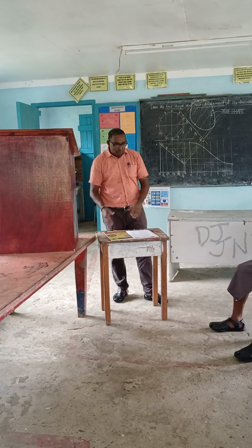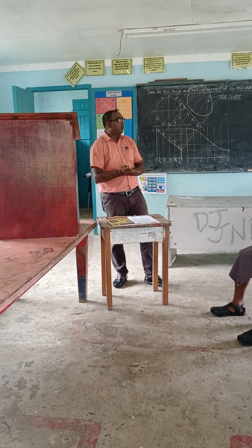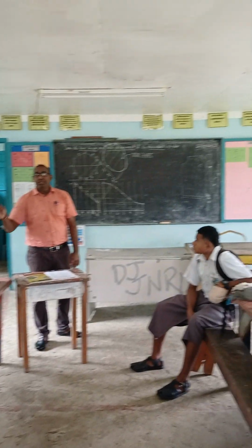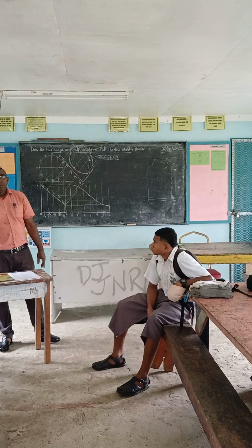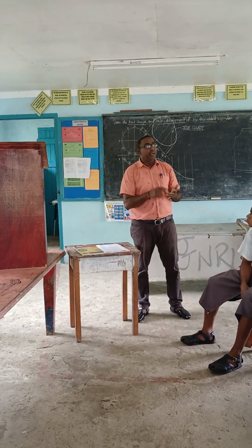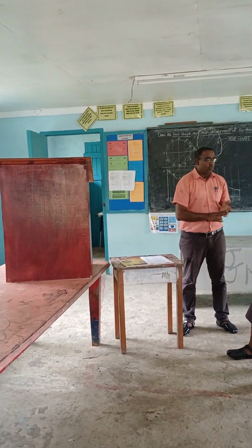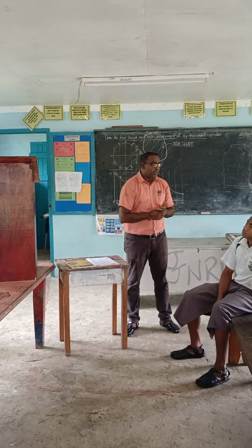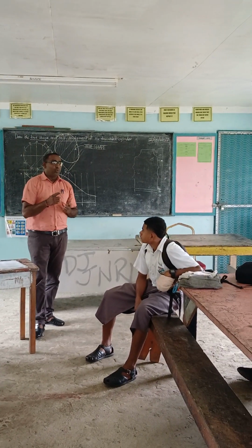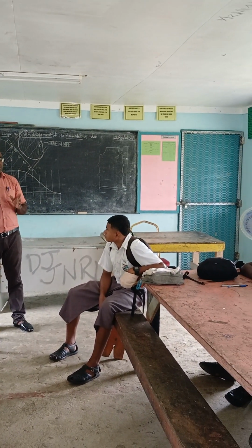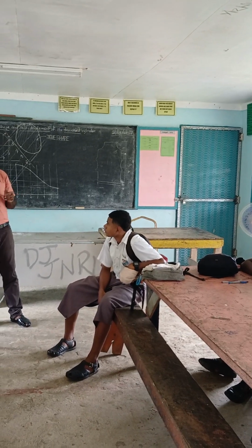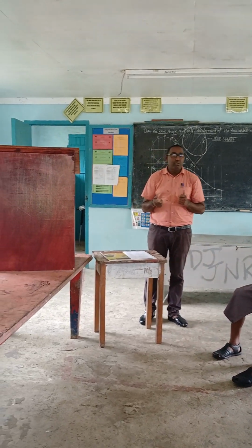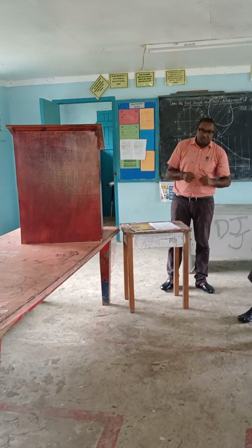Secondly, use of tools during the construction. There were certain tools that were used in the construction of the technical drawing table. Firstly, for cutting all the pieces, we used a circular saw, a tenon saw and a cross-cut saw. These three saws were used for the preparation and cutting of timbers. One thing that we need to always keep in mind when using a circular saw is that we need to be very careful, because there is a kickback of the circular saw and that is dangerous. So we need to keep in mind the safety of a circular saw.